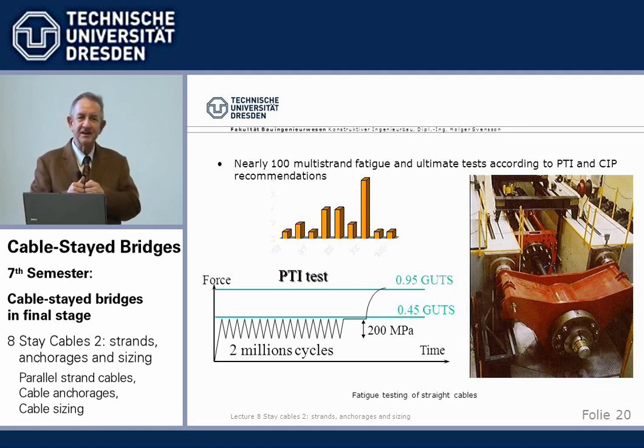So what they did, they selected by diameter, for the test cables, only strands with a plus strength. So they started already with, say, a GUTS of 105%, because they pre-selected the strands and did not take the usual ones. And then, of course, it was easy to come out with this.